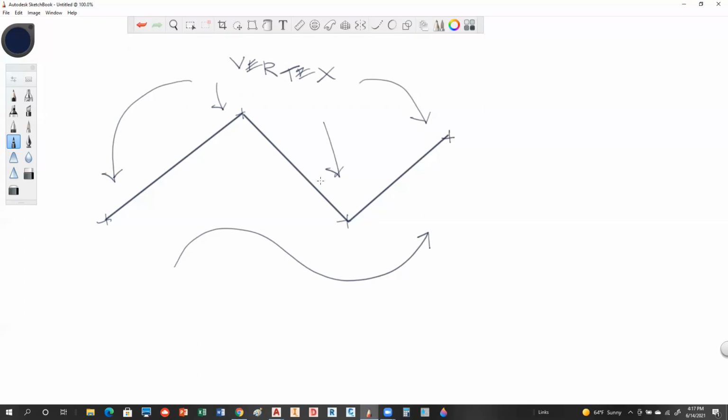These can also have width. We talked about that last week, showed you that actually. What that does is it pulls the polyline out this way and this way, and it makes it look like, some people would call that thickness, but the true term is line weight. Okay, so it gives it weight. At one time, the polyline was the only kind of object that would have this weight concept to it. Now you have line weights that you can incorporate, so that's not as big a deal anymore as it used to be.